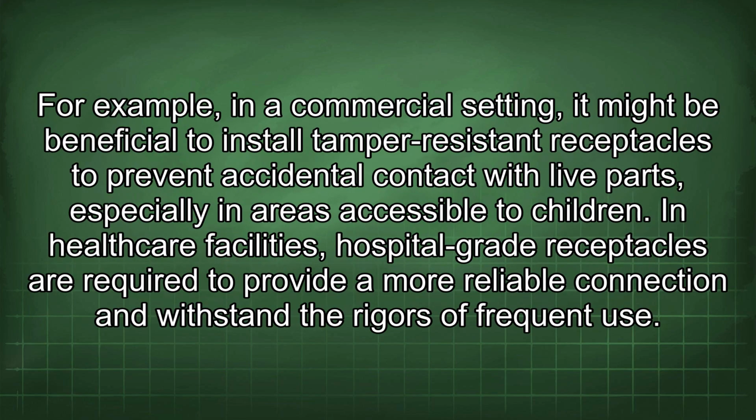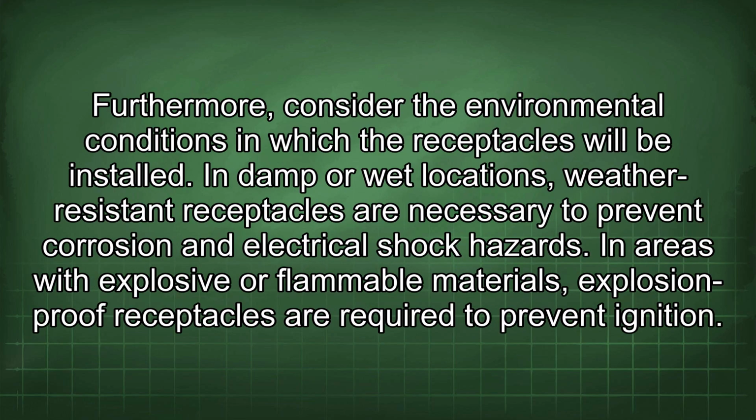selection. For example, in a commercial setting, it might be beneficial to install tamper-resistant receptacles to prevent accidental contact with live parts, especially in areas accessible to children. In healthcare facilities, hospital-grade receptacles are required to provide a more reliable connection and withstand the rigors of frequent use. Furthermore, consider the environmental conditions in which the receptacles will be installed. In damp or wet locations, weather-resistant receptacles are necessary to prevent corrosion and electrical shock hazards.